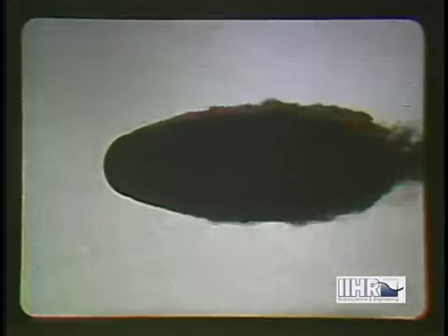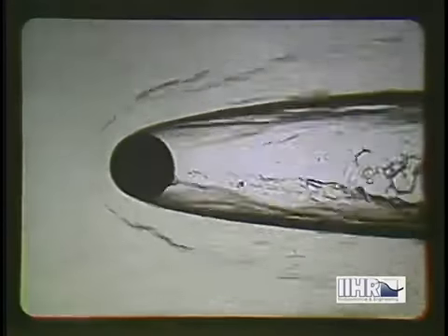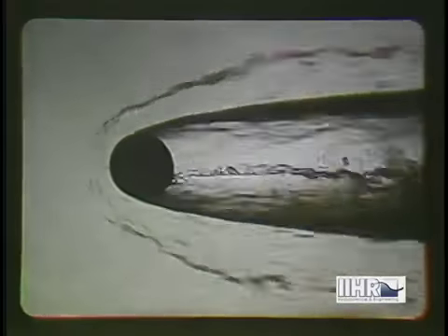Much the same phenomenon is seen to occur behind this cylinder in a water tunnel, as the velocity is gradually increased. Once the flow has become discontinuous because of the vapor pockets, neither the continuity equation nor the flow net and pressure-velocity relationship can be applied until the cavitation has progressed to such a stage that the elongated vapor pocket has become comparable to any other stable surface of separation.